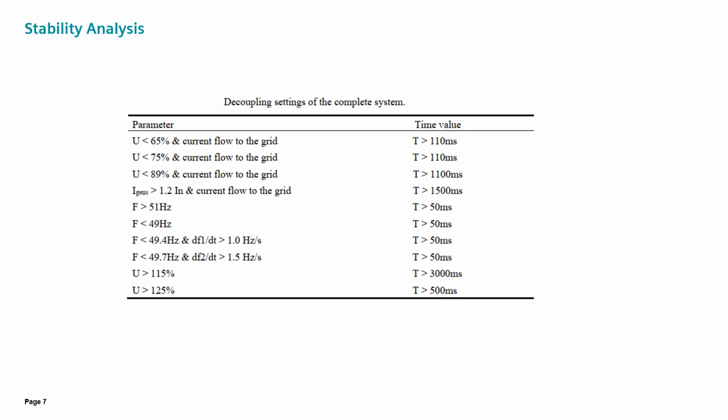The voltage schedule used for decoupling shows variance according to whether the voltage is measured from the 154 kilovolt system or the 34.5 kilovolt busbar. Since the 154 kilovolt point is directly connected to the grid, the real voltage drop is obtained. However, since there are generation units at 34.5 kilovolt, the voltage drop value observed in a possible fault varies according to the number of units in operation. Obtaining voltage information from the 34.5 kilovolt level causes a narrower band for decoupling. For this reason, it is recommended to have the measurement from the 154 kilovolt busbar, of course, if it is possible.